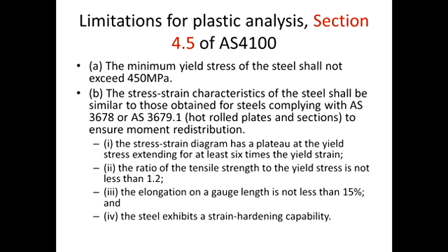And then if you have this plateau, then that plateau has to extend for at least 6 times the yield strain. And then it also looks at the ratios of tensile strength to the yield strength. So what would this be an indicator of?